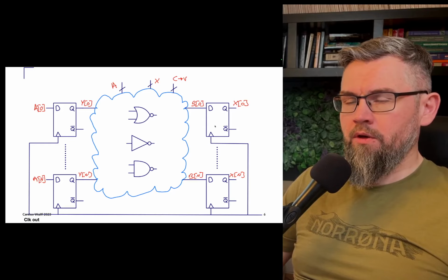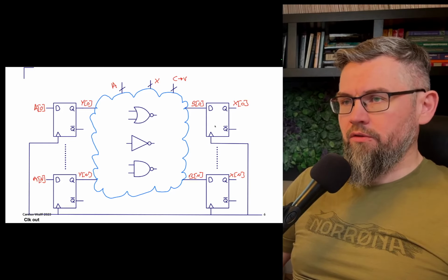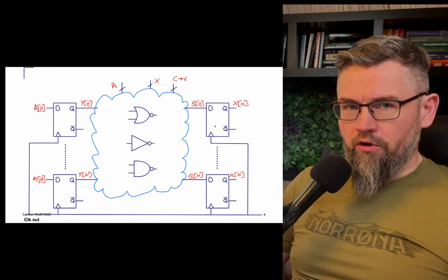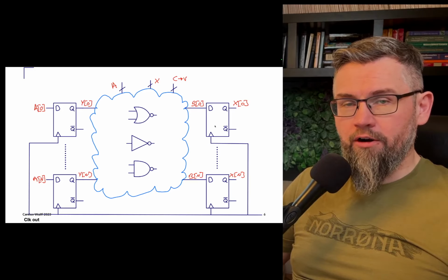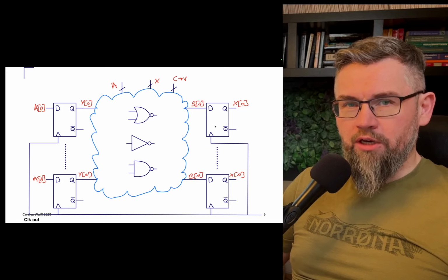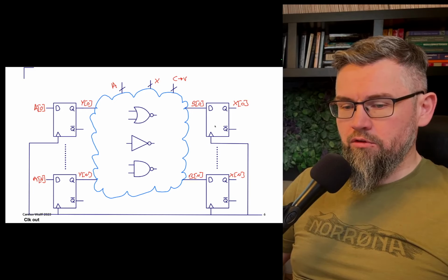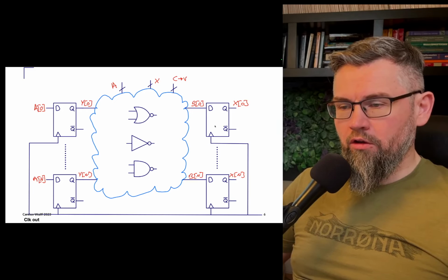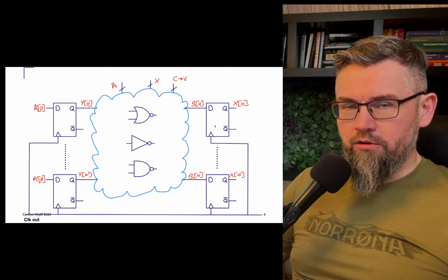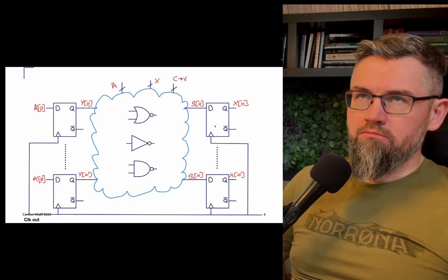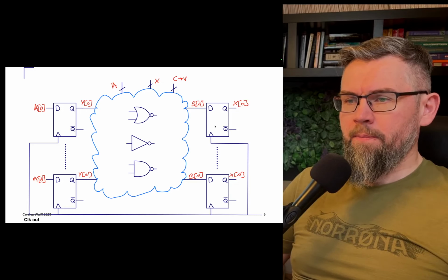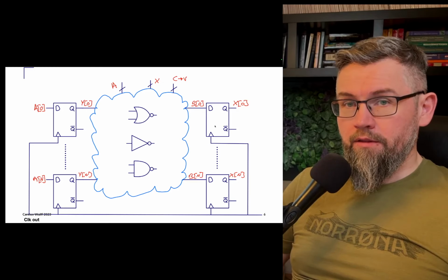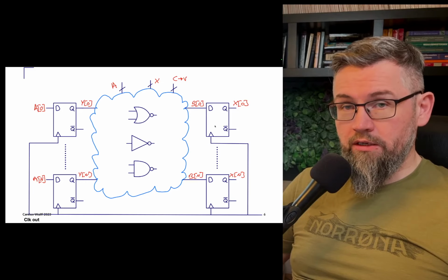And all of them need some precision, because all these setup and hold times, imagine if they vary all over the place, or if a clock varies all over the place, it becomes hard to analyze. So quite often the clock that digital relies on, it needs to be precise, but nowhere near as precise as the radio needed for the radio.